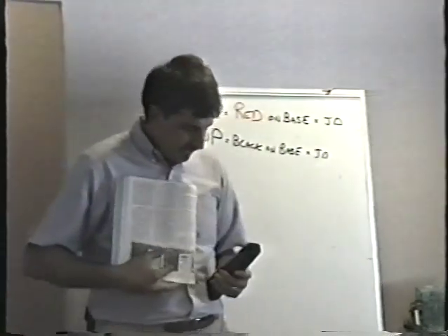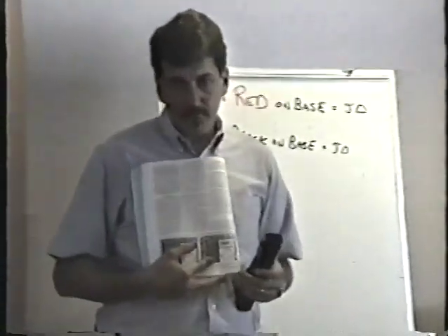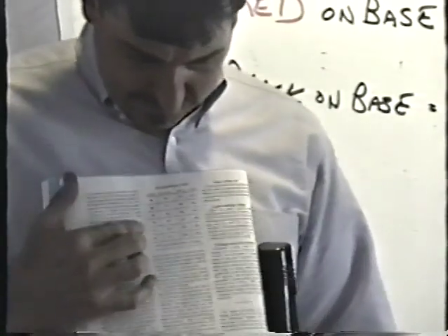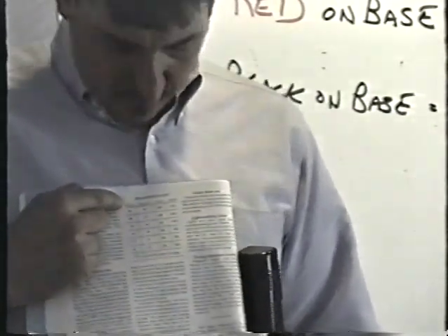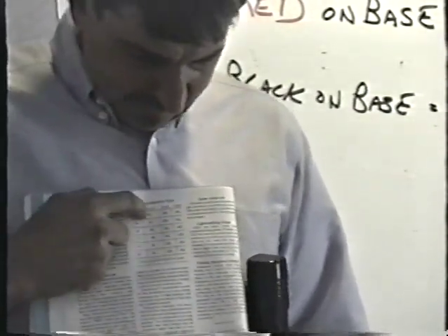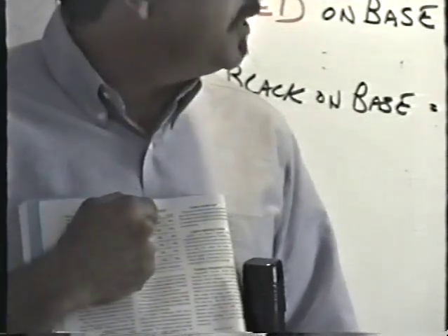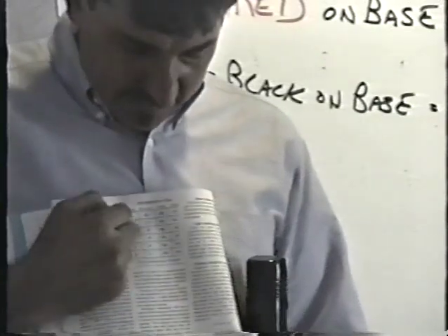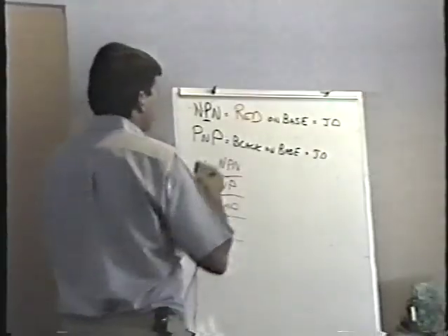When you look at the chart on the top of the page, it says red lead, put the red on the base, black lead on the emitter. If it's an NPN transistor, you'll get a junction drop. If it's PNP, you'll get an open reading. And same thing all the way down.